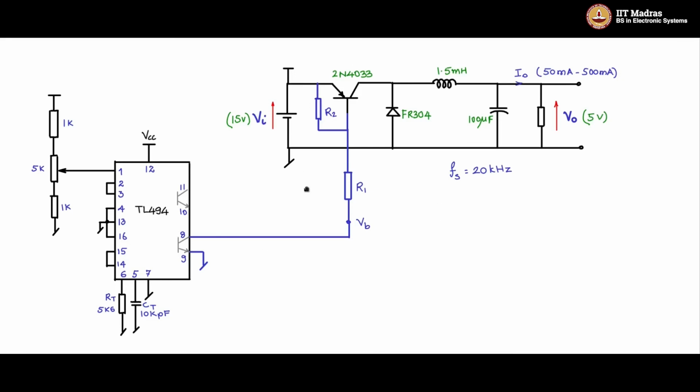But our focus here was to just demonstrate to you how the base drive works. This is a simple base drive, 2 resistance base drive and a PNP. If you use the ground side switching, you can use an NPN transistor and 2 resistor base drive. However, as you start going higher in power, you will need more complex base drives, and that's what we will look at further.